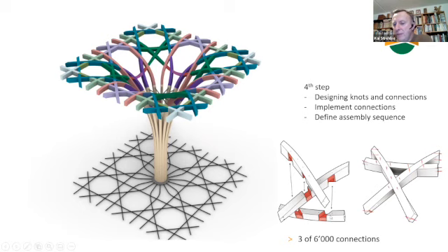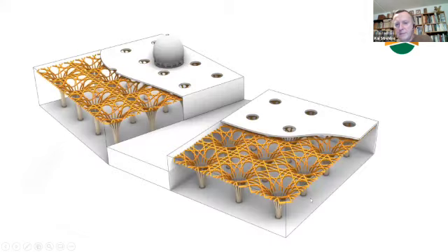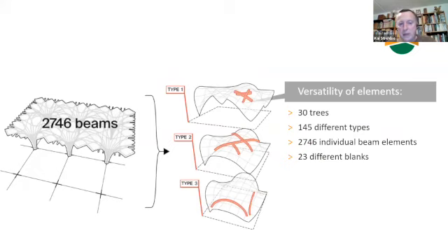But even these small lap joints are quite complicated to generate, because if you have a lap joint, you always have one direction in which you can place a segment into another segment. So if you already have two lap joints here, the geometry of these joints becomes quite complex. At that moment, we got a kind of Lego system, where we have all the parts of the building, and all we have to do in the production is produce these Lego beams.